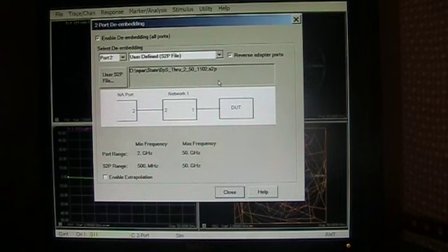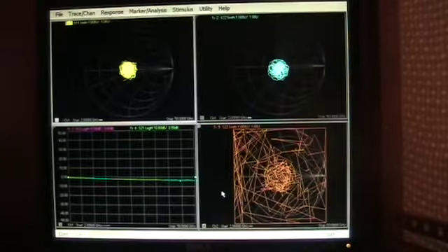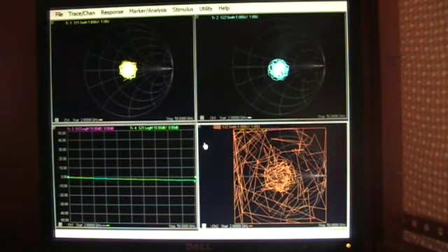That takes the measurement that we performed and drops it in on port 2. So the only thing that's remaining is from the port 1 cable down to the DUT. And this will allow us to actually take a direct 2-port measurement of the tuner and the cabling surrounding it for de-embedding. And we have to do exactly the same thing on port 2.